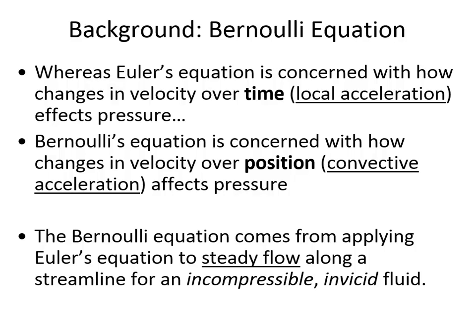What about along a streamline? Are we along a streamline in the lab? Well, how are we measuring the pressure? In the lab, we have a pipe that's big, and then it narrows down through a neck, and then it expands again more slowly to the original diameter.